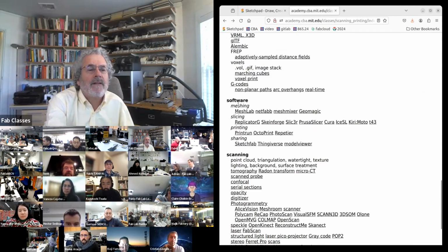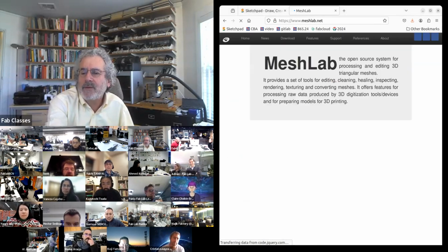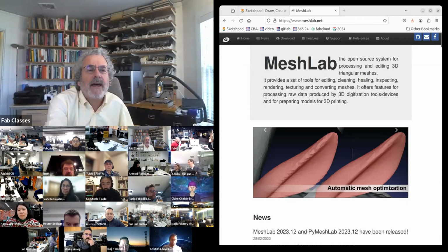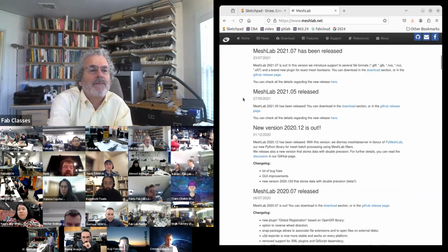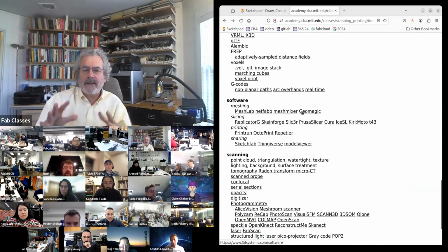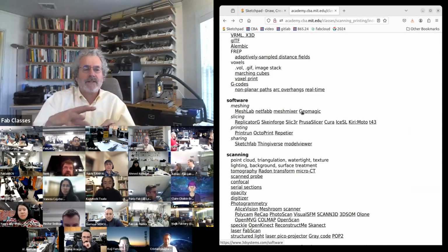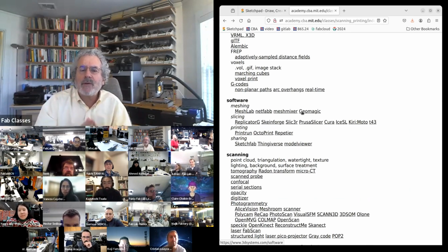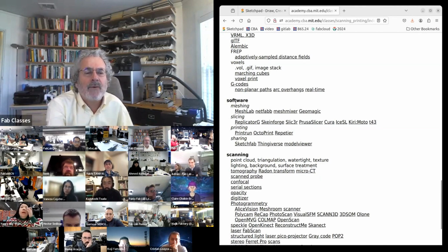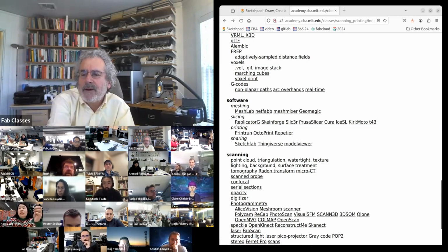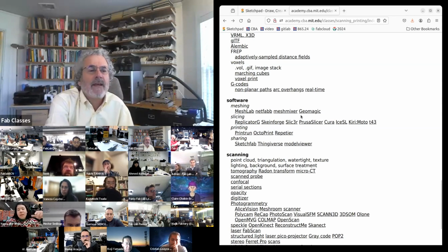So these tools, you're going to need one of these kinds of tools. MeshLab is one I like that's open source, freely available, cross-platform. What these let you do is take a mesh, view the mesh. You can do surgery on it. You can up or down sample it. And so you want to have one of these tools just to be able to understand your meshes.